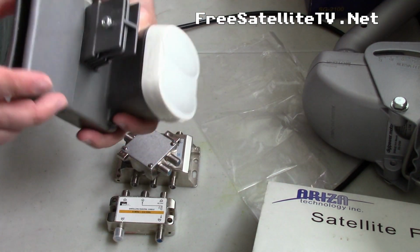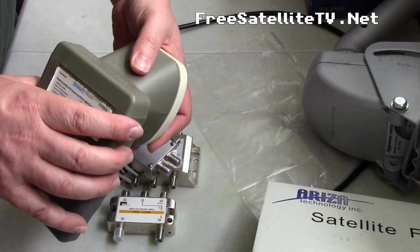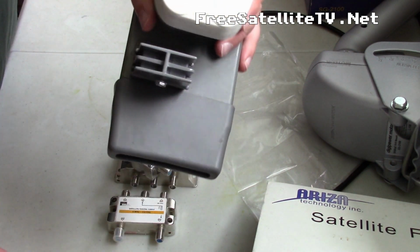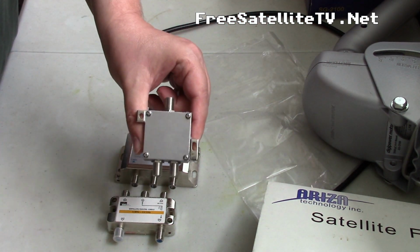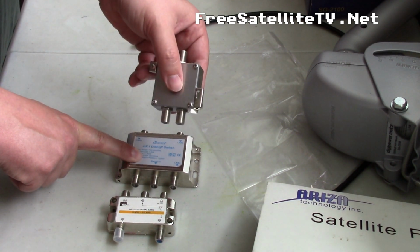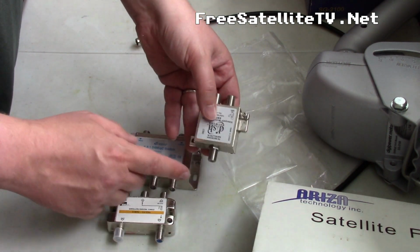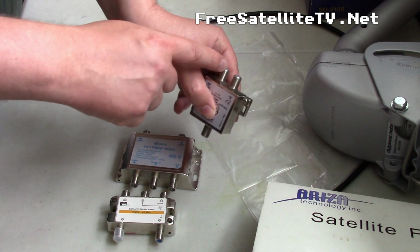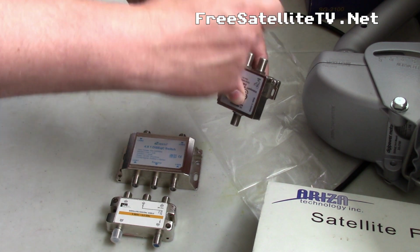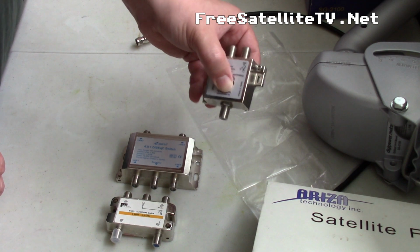These LNBs, as I always state in my videos, can be used for free satellite TV. I have one of these aimed at Galaxy 19. In the wintertime, it's great, because then I have a fixed dish right at Galaxy 19. Now what I have been able to do with one of these DiSEqC switches is, say I have a 22K switch in the one, say LNB4, and then it's going to LNB4, I can still switch it on or off, and then it will go to whatever LNB I have there. So you can have this connected to this, and then run it to a different LNB, which I did with my C/Ku band LNB when I was running that.